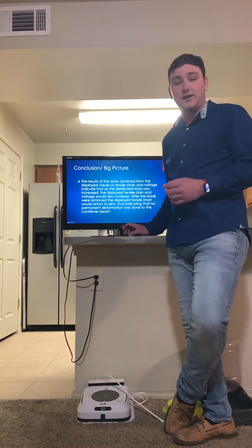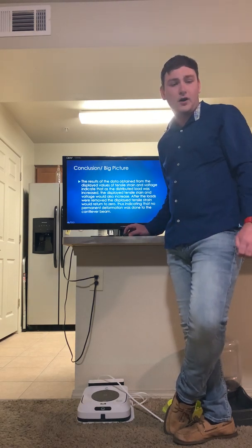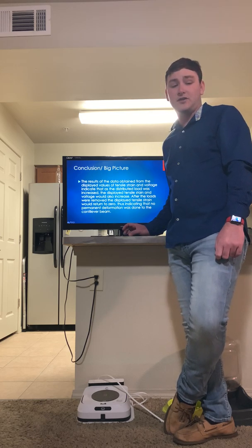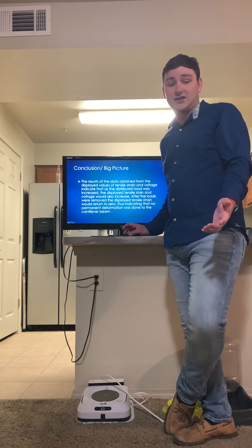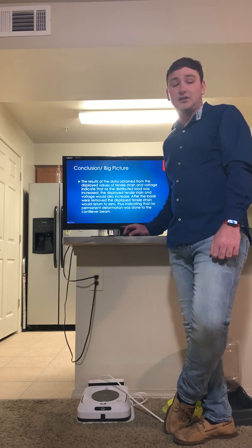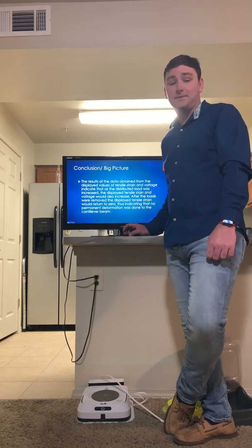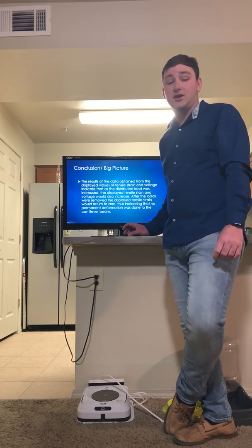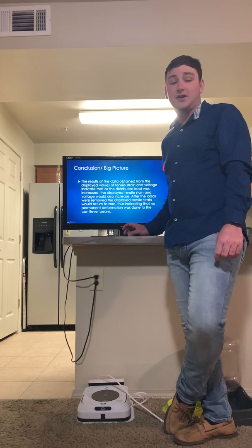So the percent difference for each of the 3 tests was close to 45%, which is a significant experimental error. This error was likely caused by the assumption of the cantilever beam dimensions based upon the equipment specifications. The assumption was made because there were no calipers to obtain accurate dimensions.